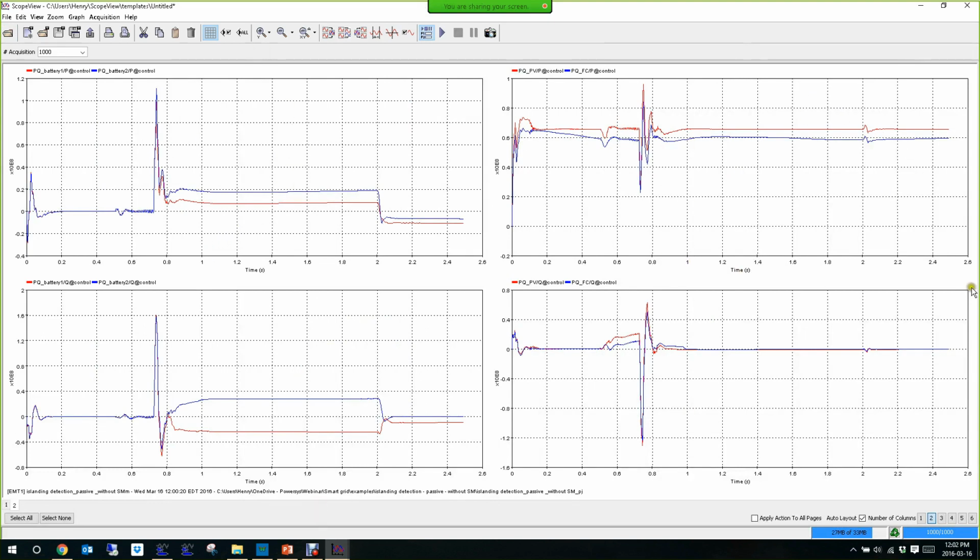Okay, so we see here the power generated by everyone. That's the power of the park. And that's here the power and the reactive power of the battery. One thing that you could find weird here, and you are right if you do: first, both don't produce the same amount of power. That's not what we want, because one will discharge faster. Also, even worse, one is producing some reactive power, and one is consuming reactive power. Which means we have rotating power inside the network. That's not what we want.